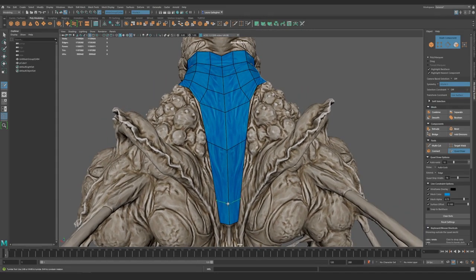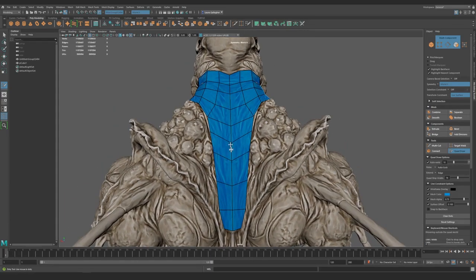I like to do this here: just extrude these very, very long polygons, and then afterward, hold control, go back in here and click to add a bunch of edge loops until I get polygons that have more or less a square shape.